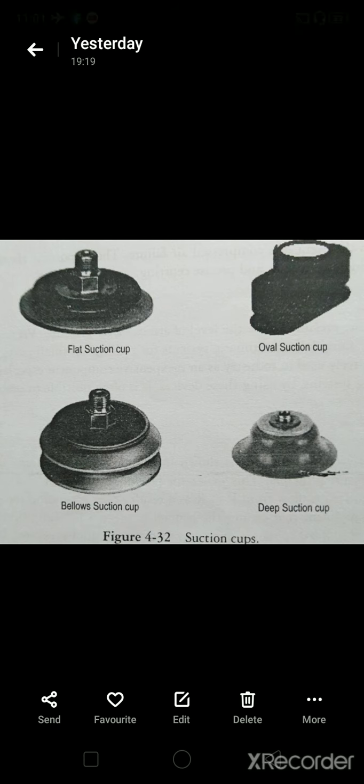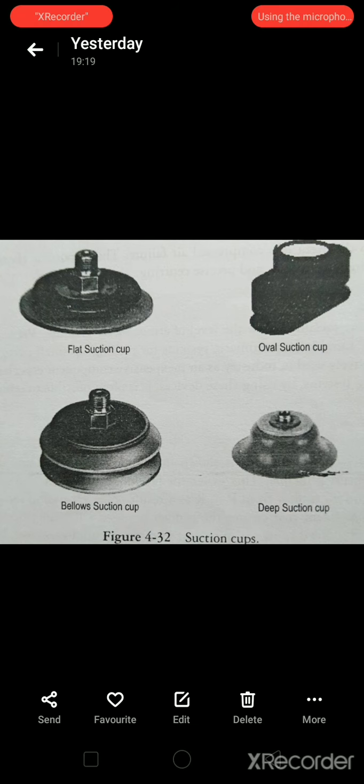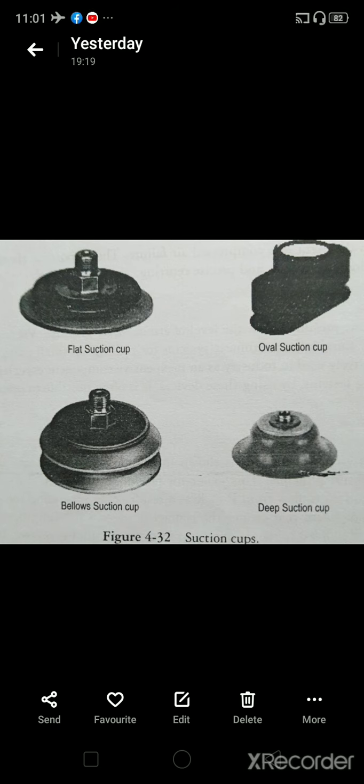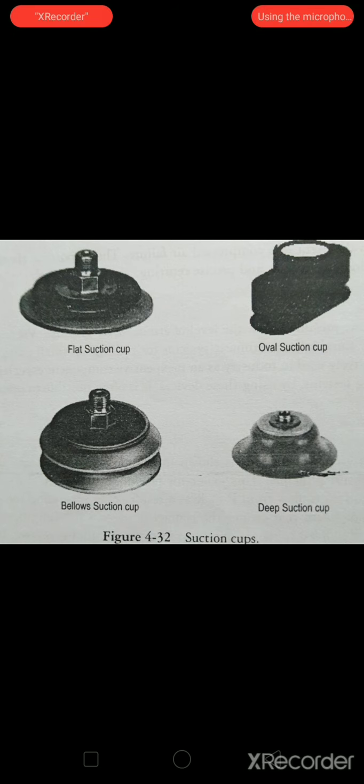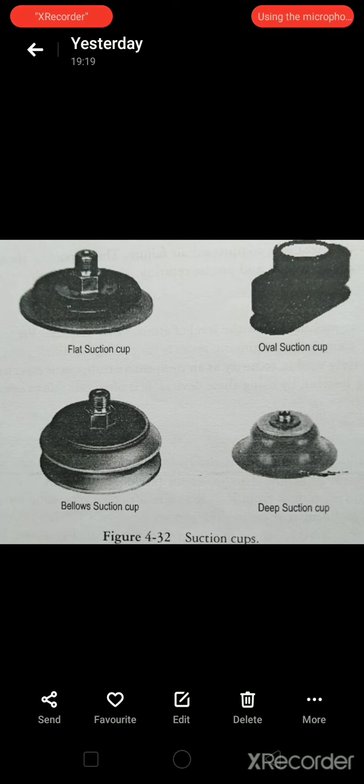The choice of suction cups is very much influenced by the intended application and the associated loads offered by the workpiece and the environment. Important properties required for suction cups are, first, resistance to abrasion, second, oil resistance, then chemical resistance, and short-term and long-term temperature resistance, which are the essential properties for a suction cup. Generally, the materials for suction cups are Buna, polyurethane, silicone, natural rubber, Viton rubber, etc. Workpiece temperature can vary from minus 50 degrees centigrade to plus 250 degrees centigrade. In an industrial environment, anything above 70 degrees is considered a special case and usually requires special material.